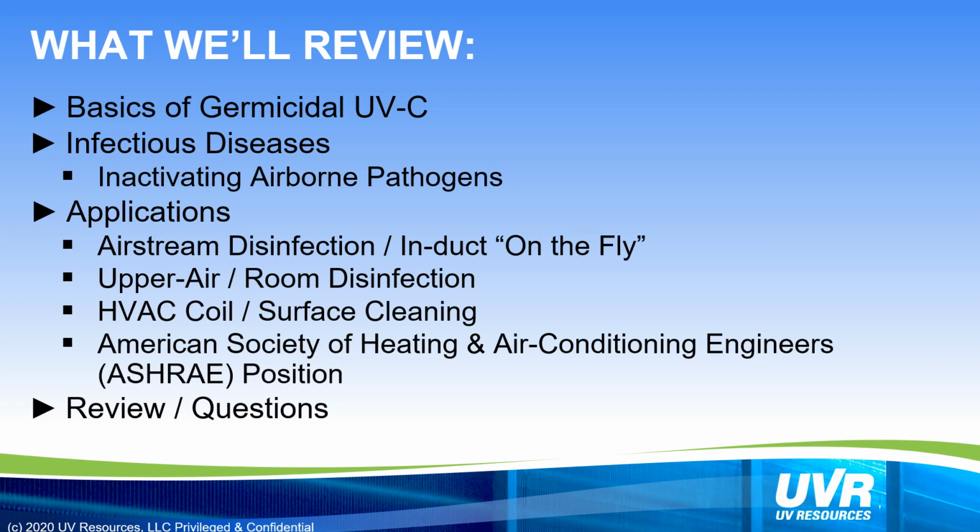What we'll review in the presentation will be the basics of ultraviolet light. We're going to talk about infectious diseases, specifically the inactivation of airborne pathogens. The applications are going to be airstream disinfection, or what we call in-duct or on-the-fly, upper room ultraviolet light, HVAC coil and surface cleaning. And if you're not familiar with the ASHRAE position documents, we want to certainly bring those to your attention and how UV plays a role in those documents. Finalize with questions and a review.